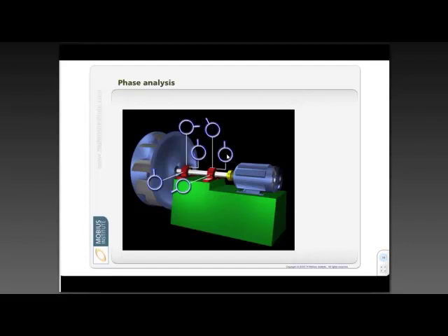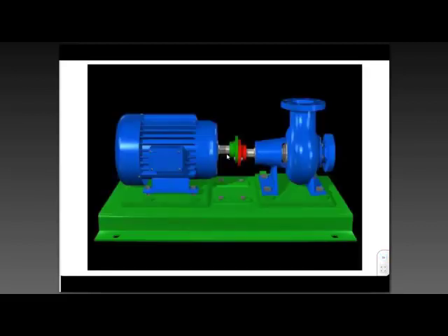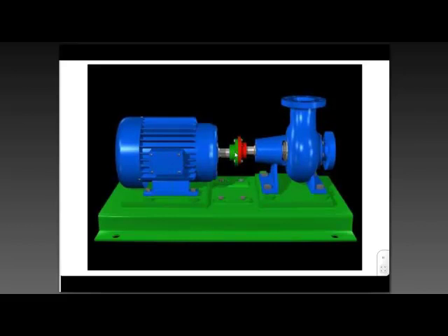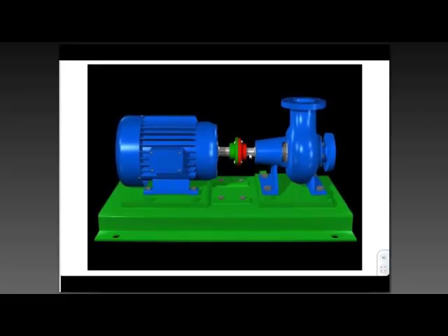A time waveform wouldn't tell you a great deal if it's unbalanced, doesn't tell you anything that you couldn't see in the spectrum for this particular fault condition, but phase gives you absolute confidence that you need to go out and balance that rotor. If we have misalignment, okay, simulated situation here, but you can see that the motor goes up and the pump goes down and vice versa.